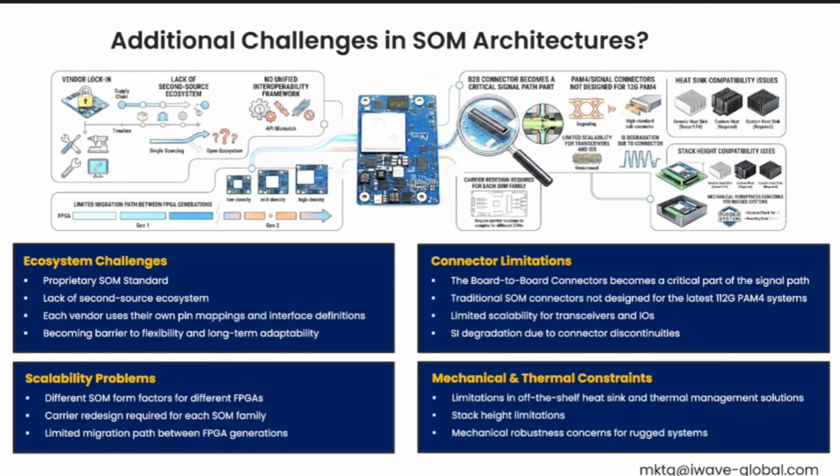And when it comes to the mechanical and thermal challenges, the modern FPGA device consumes significantly more power. As the power increases, managing heat becomes a critical design challenge. Due to proprietary SOM dimensions, there is a limitation of off-the-shelf thermal solutions like heat sinks, heat spreaders, and fan sinks. So it is very difficult to find the right solution to manage the thermal.